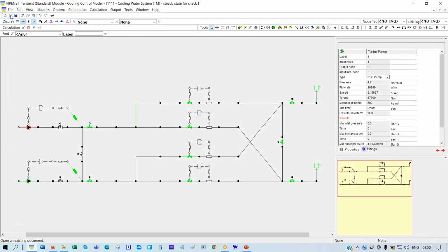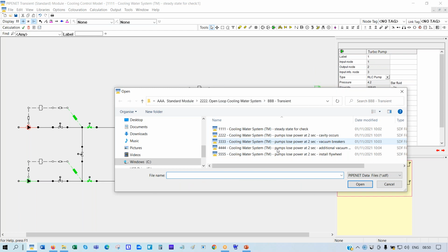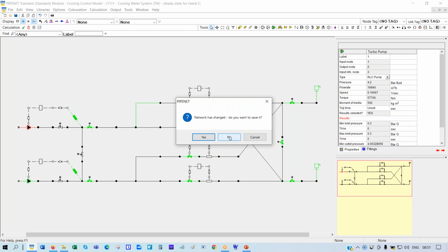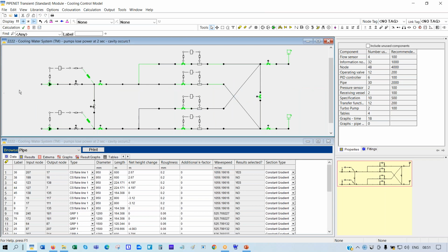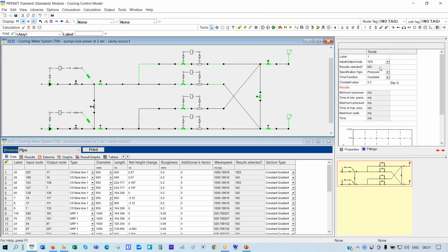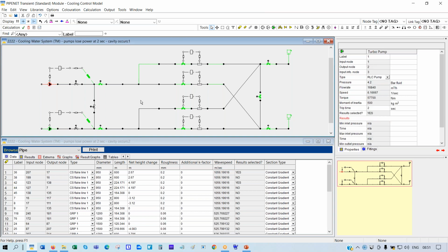And then I will just run one scenario. See, the most dangerous case with fiberglass pipes is a total failure, total power failure. And that's what I'm looking at here. See, the inlet pressure is fixed, it's the same, except the pump trips at 2 seconds.